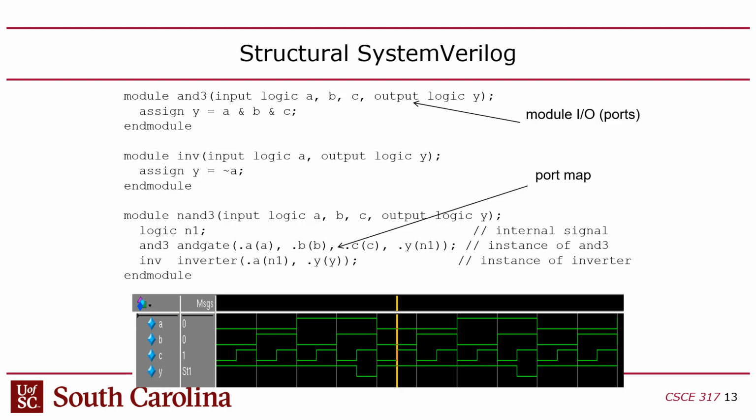So if you want to test hardware, you're going to design hardware, right? But you want to put it in this system with a Nios processor and an Avalon bus and all the other stuff. Simulation is not an option. The only thing you can do to test that is Signal Tap, right? Which kind of stinks, but there's nothing else to do. So when you guys do the hardware-based pulse width modulator, which is lab 3, if it doesn't work, that's really the only methodology you can use to figure out what's going on.